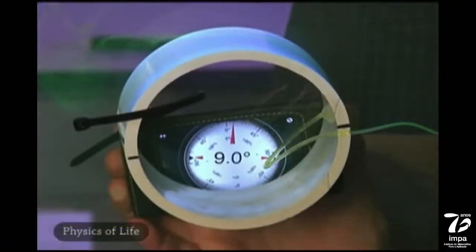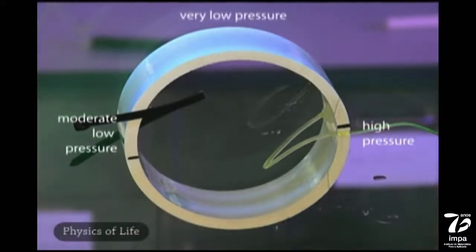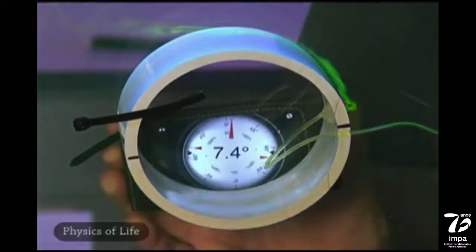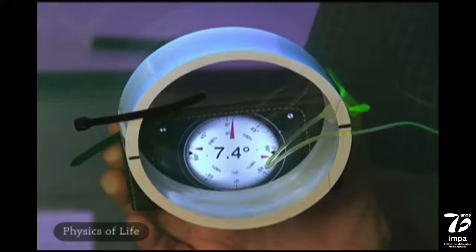Turbulence arises from the way pressure is distributed over a surface interacting with flow. According to the Bernoulli principle, pressure will be high and positive at the leading surface, but will fall to negative at the object's lateral and trailing surfaces. Negative pressures are particularly strong at the lateral surface. This imparts a complex flow in the same direction as the prevailing flow at the leading surface, but retrograde to the prevailing flow at the trailing surface. When the two flows meet, this imparts rotational momentum to a parcel of fluid. This is the origin of the turbulent vortex. Let's see if we can visualize these patterns of flow.